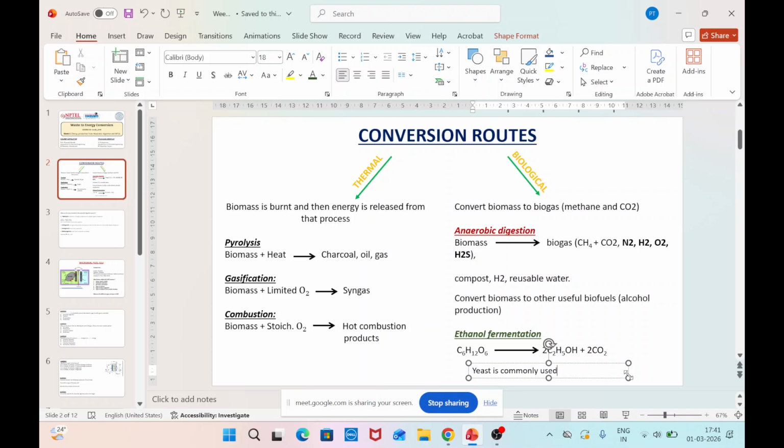So in the fermentation process, this entire breaking down of the glucose into simple sugars as well as the ethanol happens. Then you go for the distillation process, where you concentrate that ethanol so that you can get high concentration ethanol from the fermented broth. Once that ethanol is concentrated, you go for a dehydration process, where you obtain anhydrous ethanol.